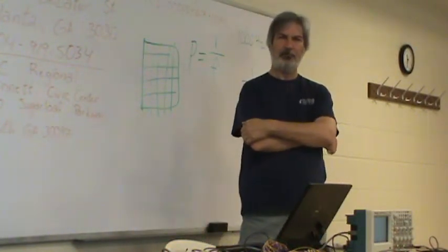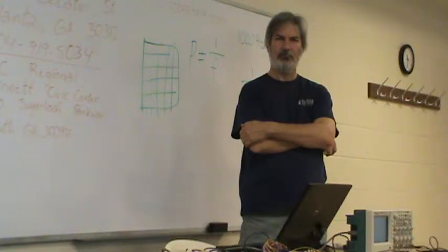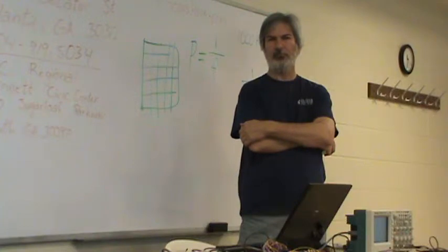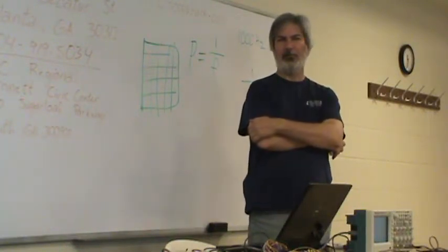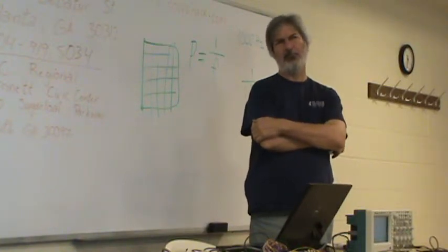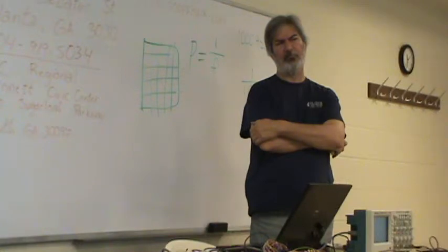But also on the triggers, I know the difference between AC and DC coupling on your signals, but the trigger on a lot of digital scopes I use also has an AC and DC option. I figure your trigger level is a level on your screen somewhere, no matter what. Well, it's typically a voltage point. But if it's AC or DC, it's still voltage. Well, say you've got 5 volts and it's got 1 volt of ripple on it, and you have to move your trigger point up to near 5 volts in order for it to start triggering on that 1 volt ripple.